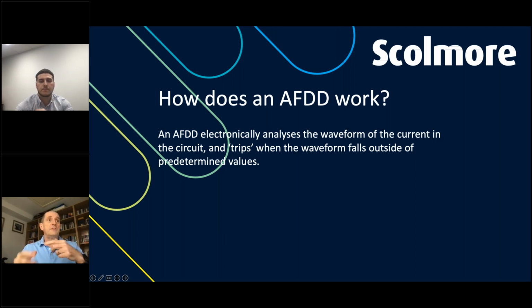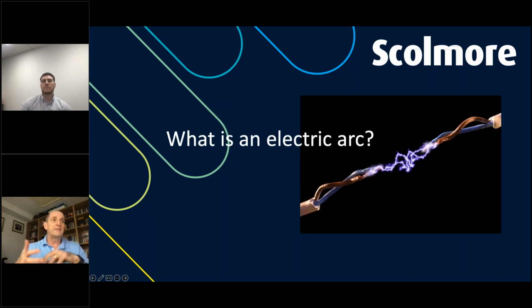And of course, Jake, if you stay here, the standard 62606 actually details the type of plugged-in device that you have to monitor against. So you've got a vacuum cleaner rated at a certain current rating. You've got switch mode power supplies, capacitor start motor, electronic lamp dimmer, fluorescent lamps, halogen. There's a whole range of bits of equipment that generate arcs of a certain characteristic that manufacturers measure against, and they are within 62606.